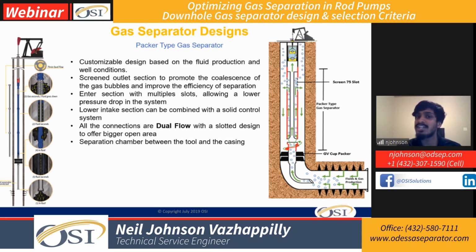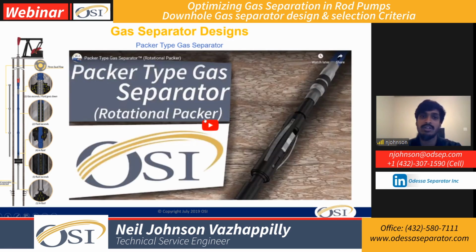And the outlet section, where we have majority, if not all, of the gas separation, where we have fluids traveling down, gas traveling upwards, and fluids going into the intake of the dip tube, and goes to the pump. So that's pretty much how the flow path works. And this is the design and some of the ways that we can improve the design of a traditional packer type gas separator. So let's move on to the video.